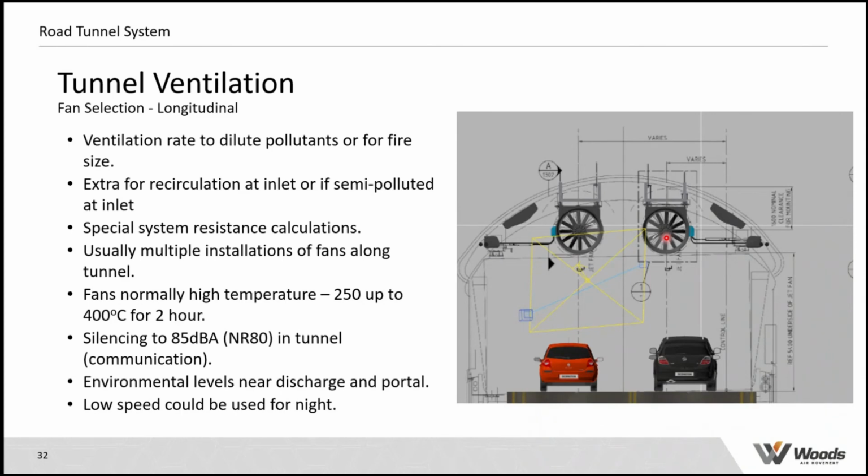Again, these fans can be rated up to 400 degrees C, depending on where you are in the world, and they'll be certified. And another important thing is, we need to maintain a noise level in that tunnel. Not when you're in your car and you're driving, but in case there was an emergency and you had to exit your vehicle, you would want to be able to hear any messages or instructions being issued from the fire brigade.